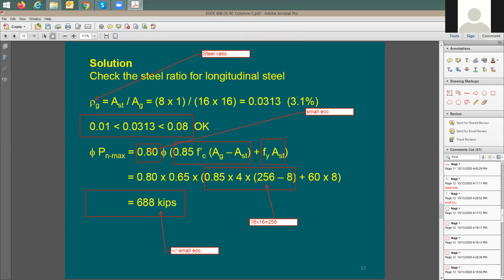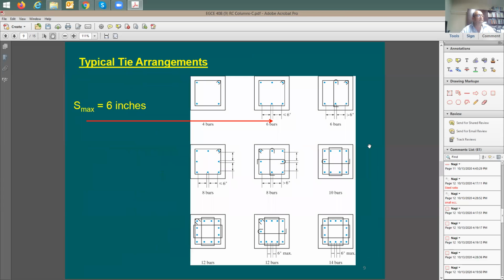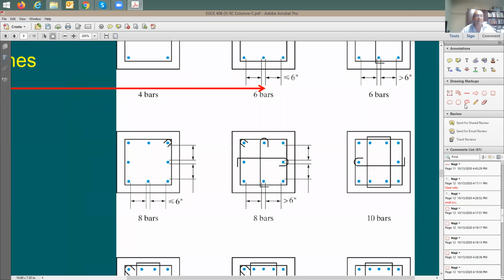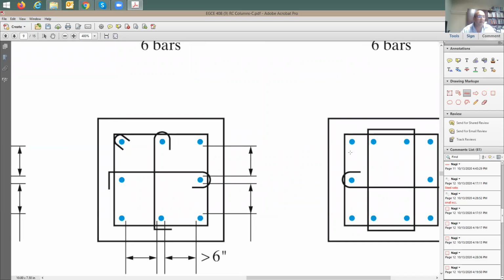Excuse me. If we have a different number of vertical rebars in 2 directions, what's going to be the minimum spacing? What do you mean? Go back to that slide with 10 rebars vertical. On those 10 bars, in the y direction we have 3, so 2 spaces, but in each direction we have 3 spaces. It depends. For any direction, you cannot be more than 6 inches. This is what the code says.